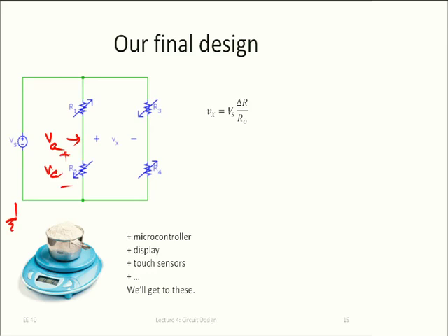Likewise, we can do the same trick here to get Vb, and then we have Vx is equal to Va minus Vb. Okay? And so I think actually there should be a minus sign here, but whatever. In principle, this equation is correct. Aside from the sign, maybe, I believe it's correct. So voltage Vx is now Vs times delta R over R, and we need only one supply. Okay, and so therefore there is not going to be a mismatch, and it's a little bit simpler and so on. Okay, so that's what we're going to build, and again in the lab you're going to build this.